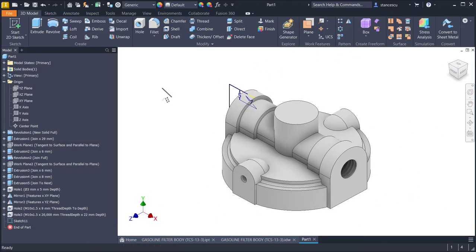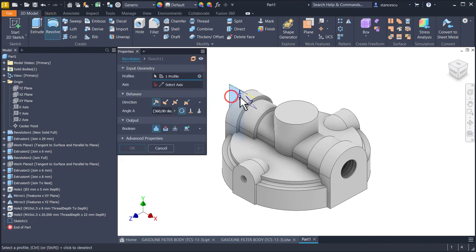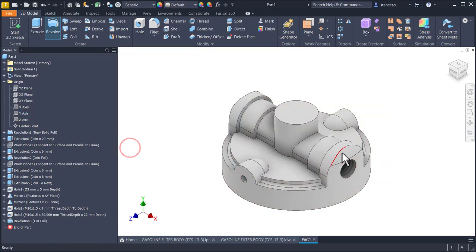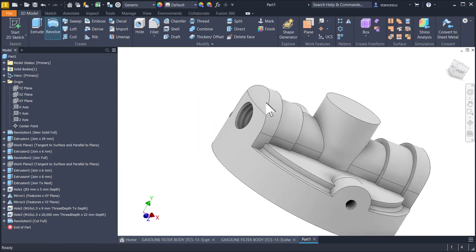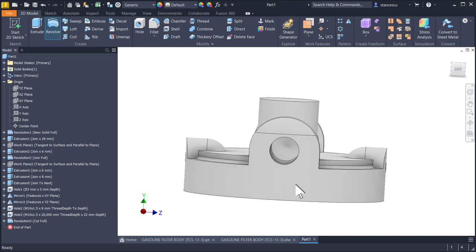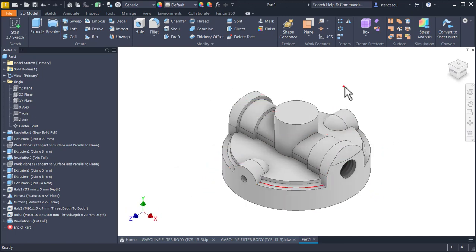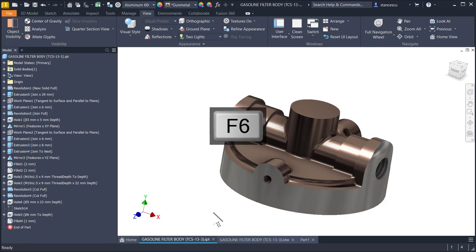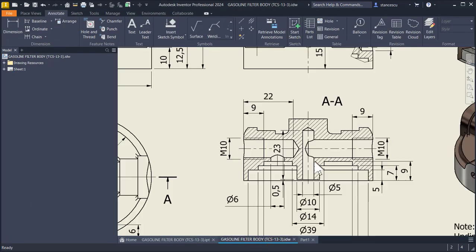Finish sketch, revolve these 2 closed areas, and the axis is Y. Not add, but cut. Okay, now we have that ending face as a cylinder. We continue with the internal volume here by using dimensions, a lot of dimensions,